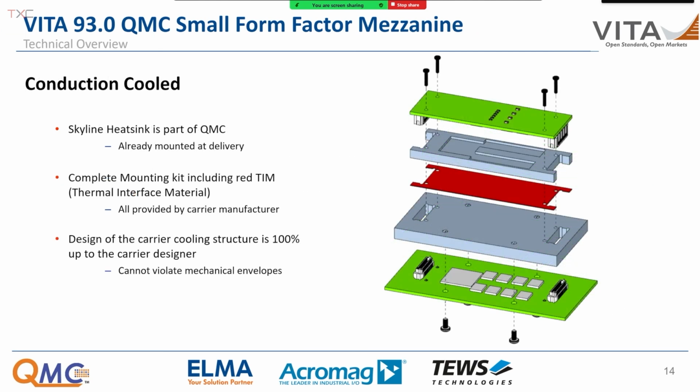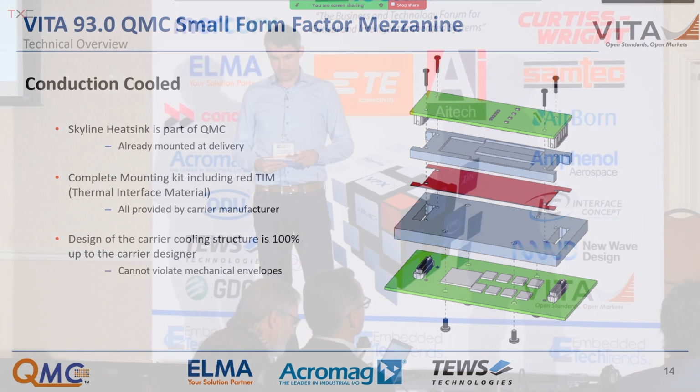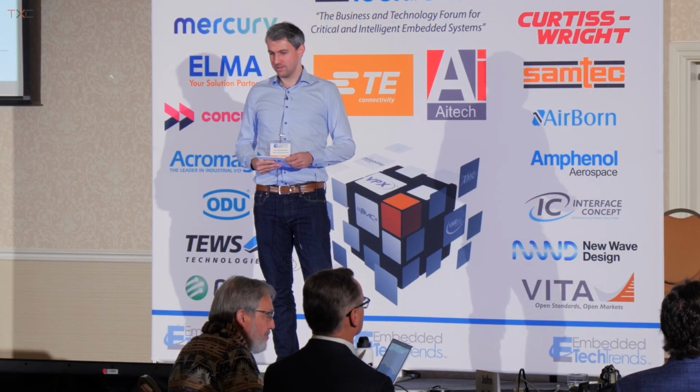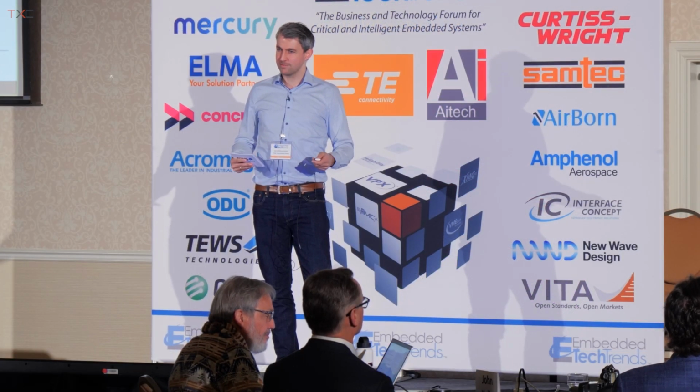Next up, we have the conduction-cooled version. Here's an example of how that may look on the right, where you have the carrier on the bottom and the QMC on top, together with the Skyline heatsink, which is the only mechanical part that comes with the QMC and is usually pre-mounted. Then, once again, as with all the other QMCs, all the mounting hardware comes with the carrier.